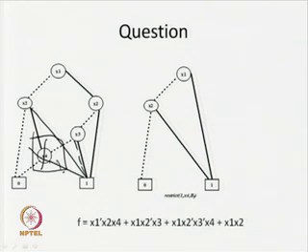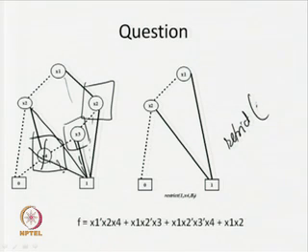Now, just try to see the rules. When I come to this x3, we find that it has a redundant test, so we can remove it. After removing it, the incoming edges will be redirected over here. Again, when I look into x2, we will find that this is another redundant test. We are going to remove it. After removing it, the solid edge will be redirected to this particular one. So, eventually I am getting this structure. So, this is the structure for restrict 1 x4 of f.